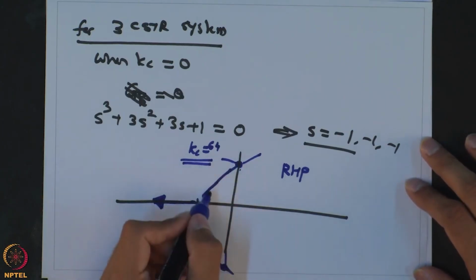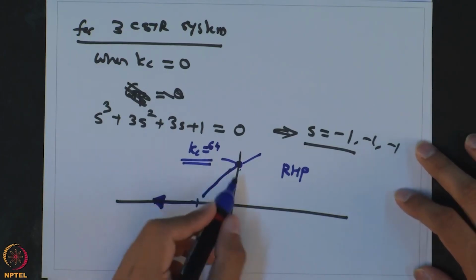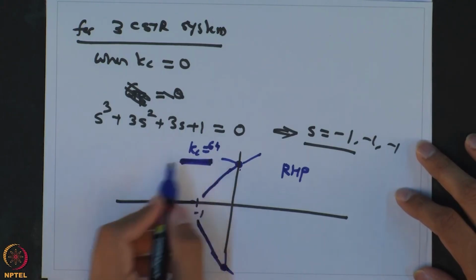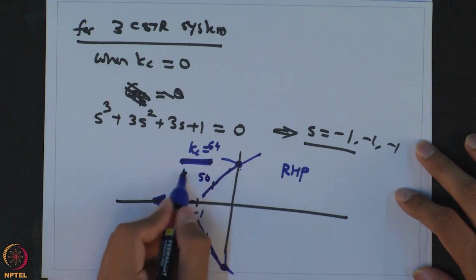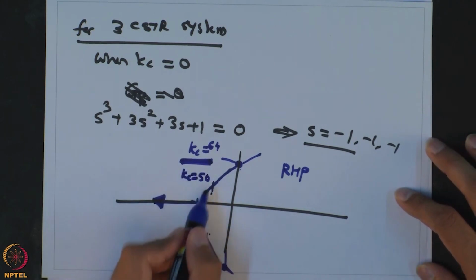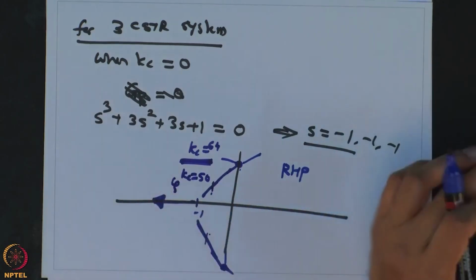So, the root locus diagram additionally gives you information about what the response of the system looks like even when the controller gain value is less than 64, let us say some value around 50. It will say that the system will have decaying oscillations. It will also tell you the corresponding damping coefficient. So, you can also calculate the period of oscillation and all those things. The root locus diagram condenses all this closed loop information along with the limit of stability.